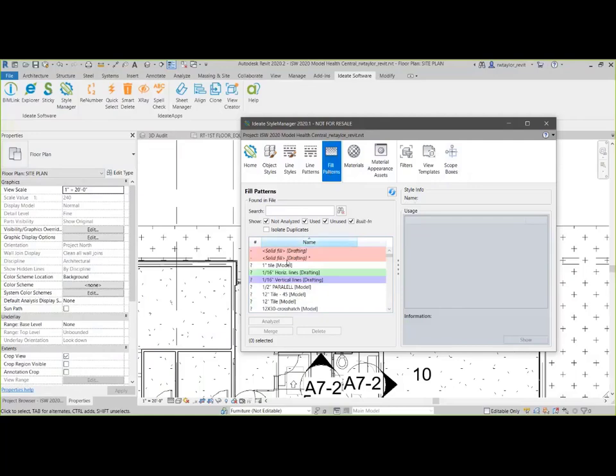It's showing me all the fill patterns that are in this project, right? So as you see, there's a lot of them. So in order to focus on what I want to review, I might want to use the search dialog, and I'm going to look at just sand. So when I type in sand, it gives me 4 patterns that have been defined for sand, right? Sand dense, sand drafting, sand small.